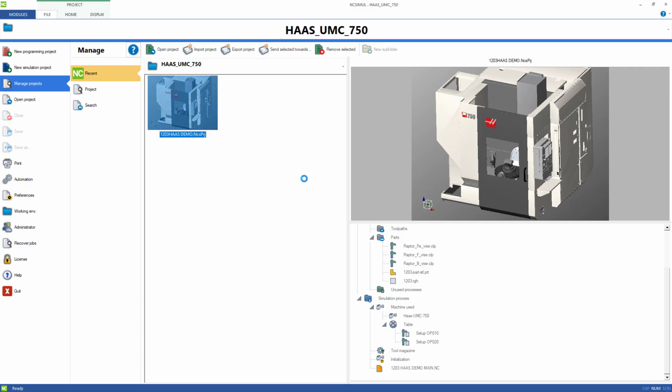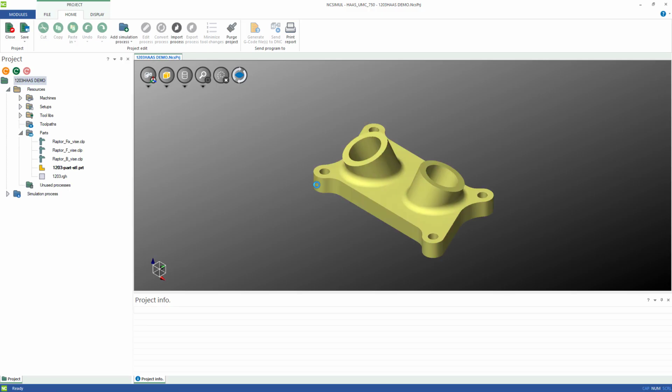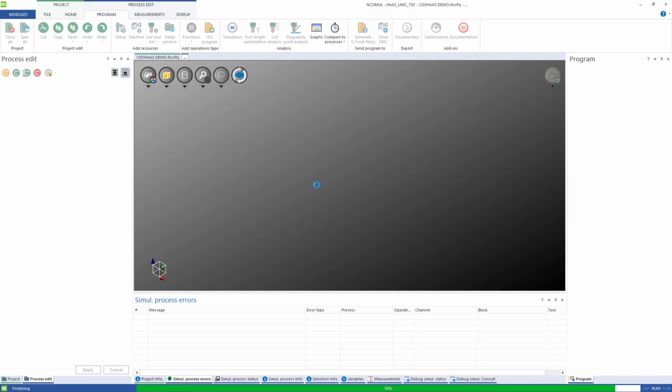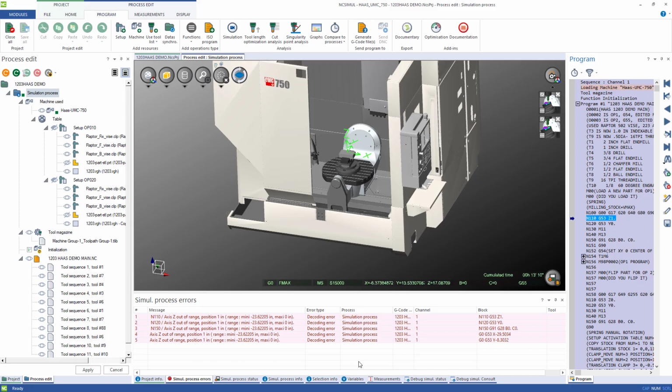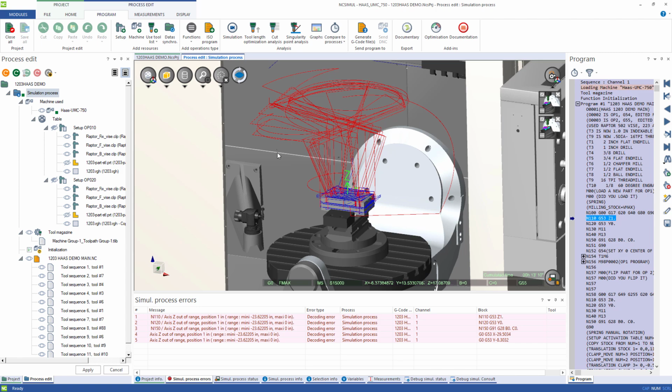If I do double click, it starts what we call the 3-step process. So step 1 was that syntax error check. Anything that would alarm out the real machine is getting defined up front, and you'll see all those errors coming into the information window at the bottom automatically. And then as I was saying, the toolpath wireframes get populated automatically. So there's the screenshot we saw at the very beginning, and you can verify that you're in the right location at the machine before we even get going.